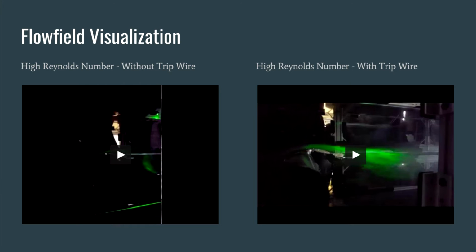In the case of a high Reynolds number with no tripwire, we see the boundary layers beginning to transition from laminar to turbulent. By this time, however, the vortex street is mostly, if not fully, turbulent. At the Reynolds number we ran this part of the experiment at, both these flow characteristics match up with what is generally accepted. While turbulent, the wake remains wide and somewhat organized.